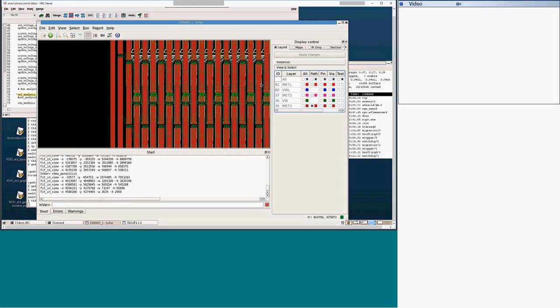Okay. The reason he got rid of poly: I asked him where it is expected to have IR drop, and he came to the conclusion that poly here is like gates, and gate has small content, and mostly we should be concerned about metal layers.